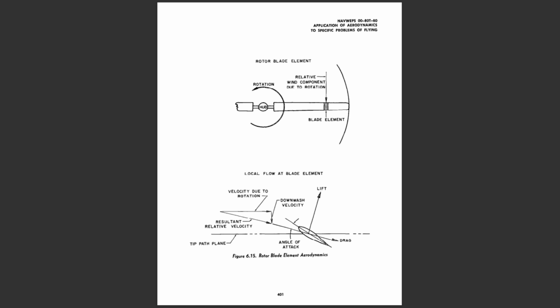The lift coefficient is identical to that used in airplane aerodynamics, while the solidity is analogous to the aspect ratio in airplane aerodynamics. The rotor torque is found to be proportional to a non-dimensional torque coefficient, the air density, the disk area, the square of the tip speed, and the blade radius. The torque coefficient is dependent upon the average profile drag coefficient of the blades, the blade pitch angle, and the average lift coefficient of the blades. The torque can be thought to result from components of profile and induced drag forces acting on the blades, similar to those on an airplane.